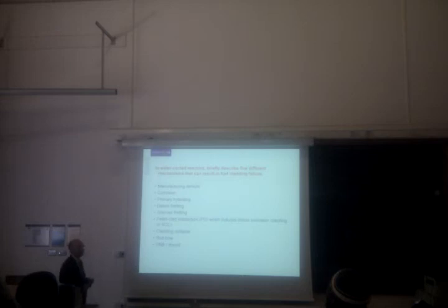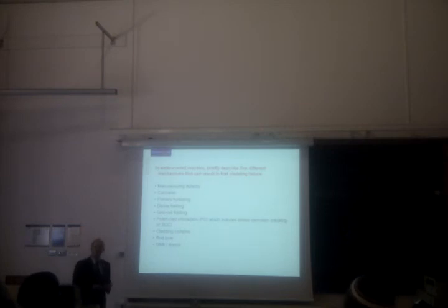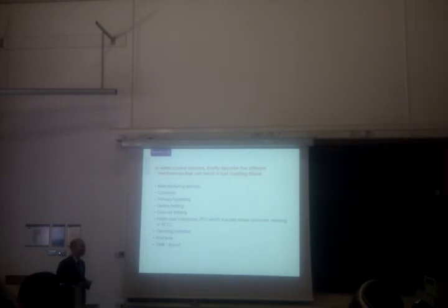Corrosion is the process of taking up oxygen by the cladding, so the water is reduced, hydrogen is liberated, and you might remember that zirconium has a particular affinity for hydrogen. It's like a sponge, it sucks it up. It won't do that indefinitely. If we continue to add hydrogen to zirconium metal, then it's a bit like adding sugar to tea. Eventually, the hydrogen will become saturated in the metal.